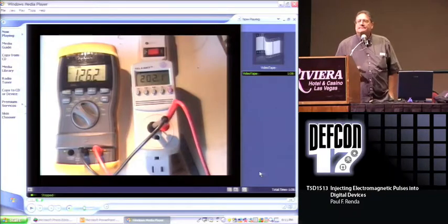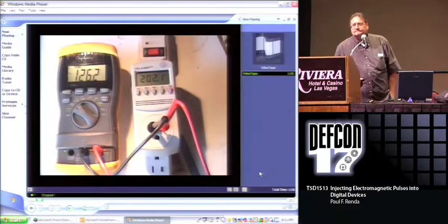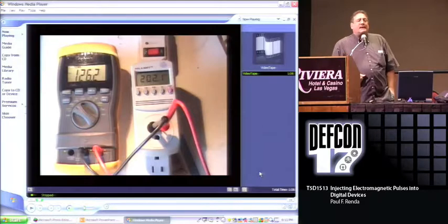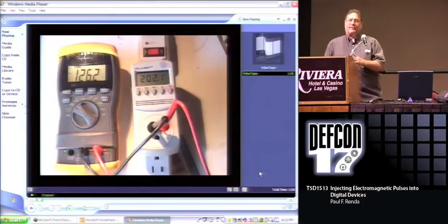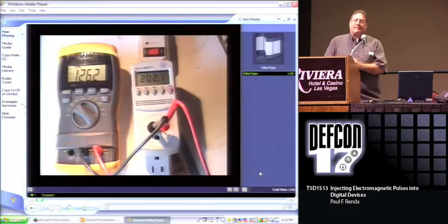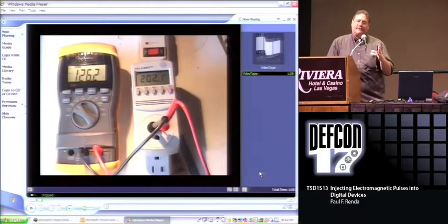Anybody else? Yeah. What about pulse rate? They're about IGBTs. They do high pulse rates, typically break down around 15 or 18 kilohertz. So what do you pulse it? If I use it for a Tesla coil, I would not try to control the pulse rate through the coil itself. I try to control the pulse rate through some type of mechanical device that is basically arced. In other words, some type of rotating device or something of that nature.